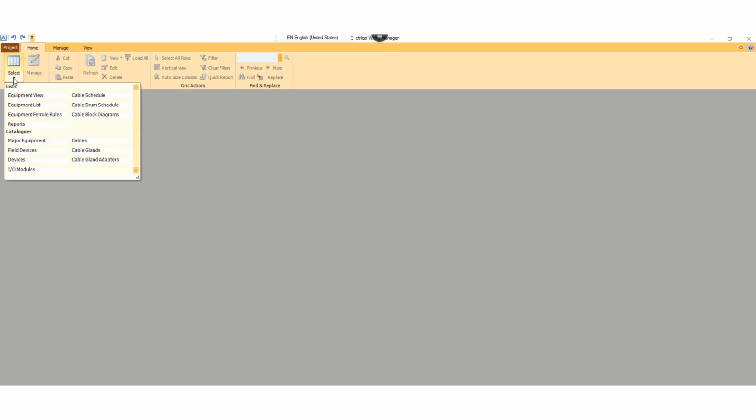With the help of AVEVA Wiring Manager, we can create a cable schedule and cable list. So first of all, we have to go to Catalog. As a first step, we have to create a cable catalog. So under Catalogs, let's click here, Cables.